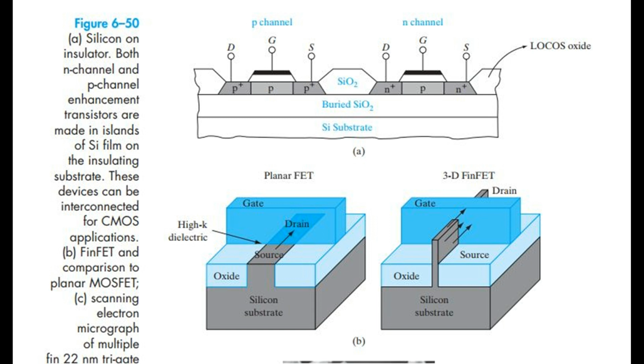B. FinFET and comparison to planar metal oxide semiconductor field effect transistor. C. Scanning electron micrograph of multiple Fin 22 nanometer tri-gate field effect transistors connected in parallel to increase the effective width.